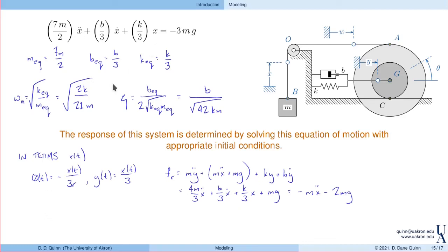Finally, a little bit more, we could determine the static displacement. So the static displacement is the solution to the differential equations that doesn't change in time. So basically x of t would be some constant value, delta. I'll just use delta as the abbreviation for the static displacement. But I've got to solve for delta. Okay, delta doesn't change. It has to solve the equation of motion, so this term would go away. Again, delta's constant, acceleration's zero, and it amounts to solving what's left.